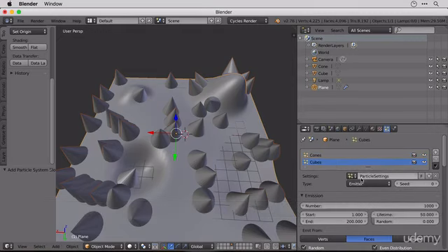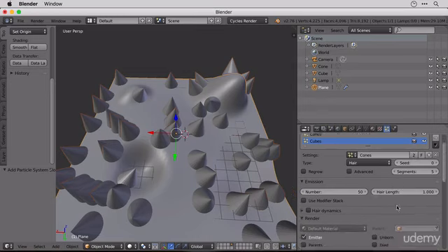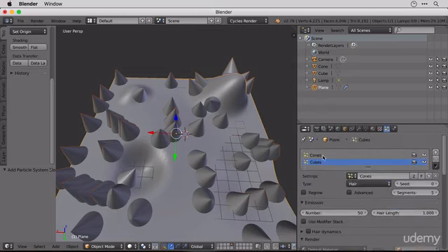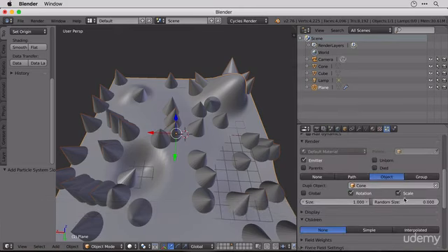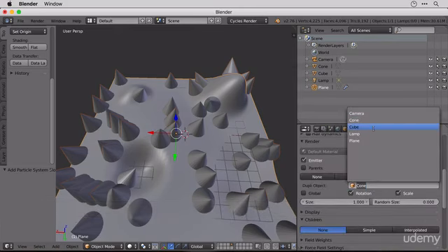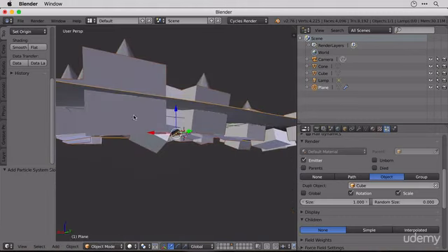And if we go here, and we are talking about cubes this time, we can borrow the cones. Now we need to make it unique by clicking on this number. Otherwise, anything we change down here will change both of these particle effects. So let's go down here and press the number 2. It changes to cones 001, and I'm going to rename that immediately cubes. Now it looks no different at the moment because we do need to scroll down to the object and change it to cube. And you can see here that we've still got the same problem with it being half-half.